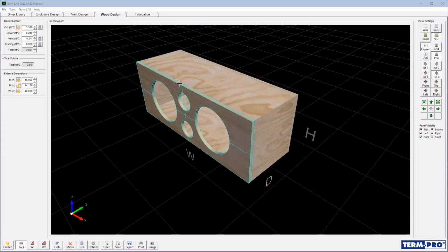Now, one of the benefits of individual partitions is that you have additional bracing, because when you put a partition in there, it makes this panel a lot more rigid. But you could easily add some bracing to the box yourself. Another advantage to individual partitions is if you have a sub failure or an amp failure, it doesn't impact the system as much as if you have a dead woofer that literally is acting anti-phase to the rest of the driver.